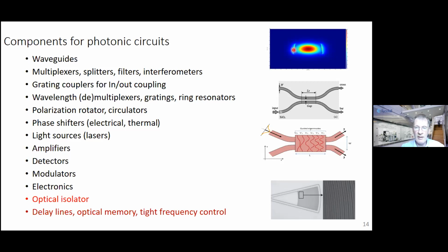So it's got a certain spread, and you need to confine it. So you need a high index material surrounded by a low index material in order to confine the light. So you can make a wire for light. So you make the light go along a wire. And one of the problems with photons also is that the curvature of the wire is very significant. You have to be very gentle with photons. If you go around the corner too sharply, the light will splay out and you'll lose light, and therefore you lose energy.